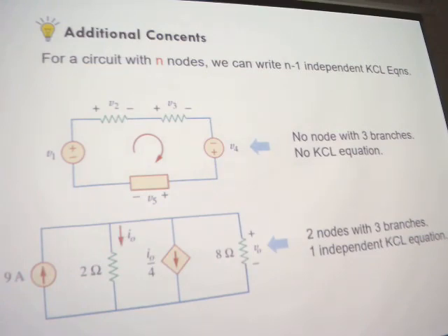Okay, so for this figure, do we use KCL law or KVL law? 2 nodes. So for this one, we can say it is no KCL equation because we didn't have any independent node inside. Because, for example, we take one from here. Okay, take one from here. We can say the current going inside is equal to current go outside. So the KCL equation has no meaning.